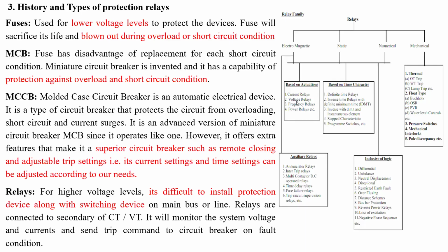Then later they introduced numerical relays. These are the latest version of the relays. One numerical relay can have multiple protection functions as well as control functions and metering functions. This is the main advantage of numerical relays, which are available with different protections like differential protections, transformer differential protections, REF protections, and bus bar protections. There are a number of types of relays, and the manufacturers are ABB, Siemens, T&D, and GE. These are the main manufacturers of numerical relays.